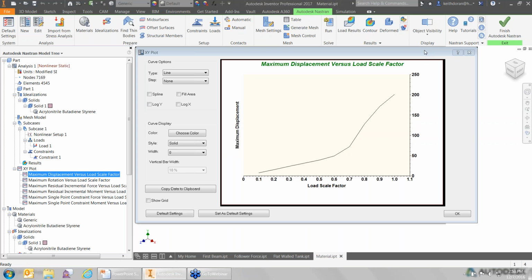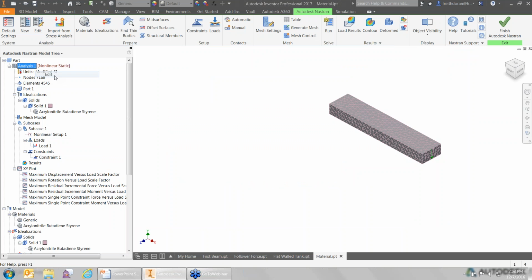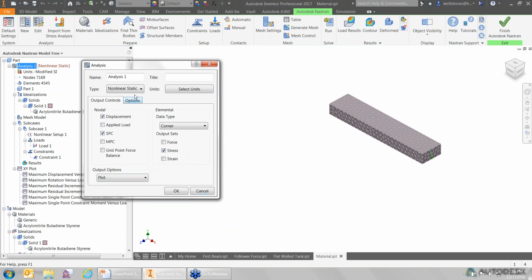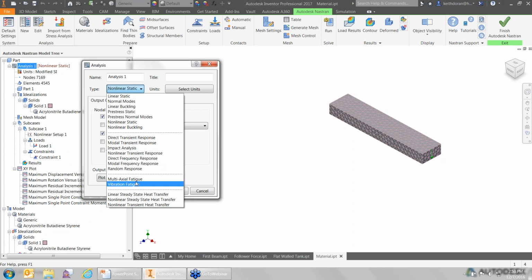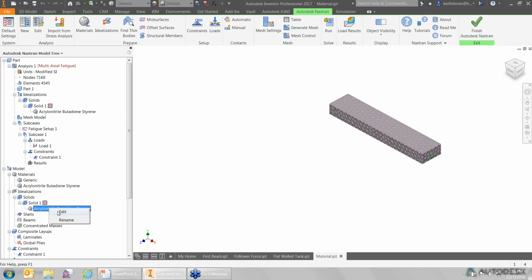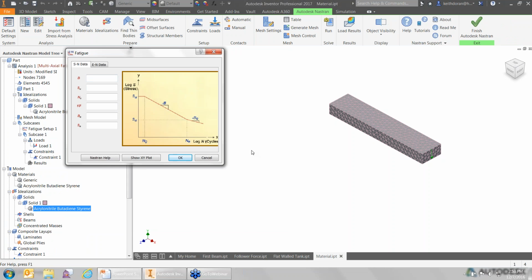And just to take a look at that here inside of the environment, the first thing we would do is change the analysis type. And one of our types within this space is our fatigue. We'll just do fatigue. And then beyond that, the material itself has a fatigue SN curve that we can build. So you have the SN data or the EN data, depending on what pieces of information you know about the component, what type of material you're dealing with.